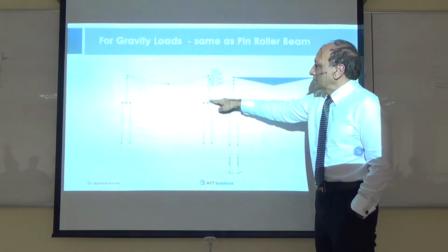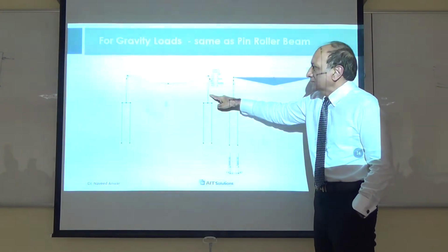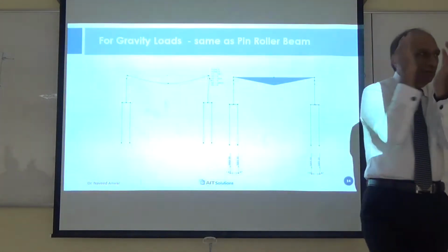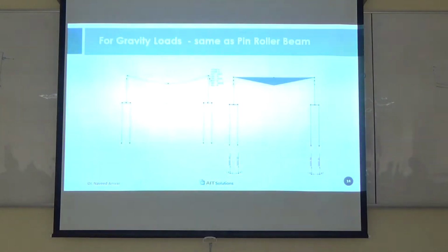But we have some bending moment in the column coming from that displacement, so that roller is moving the column, so the column will try to bend, so we can calculate. Which means that vertical load on the girder will actually create bending moments in the pier, which otherwise you cannot imagine if you use a simple pin roller condition.